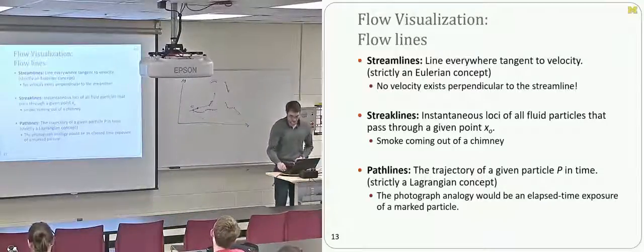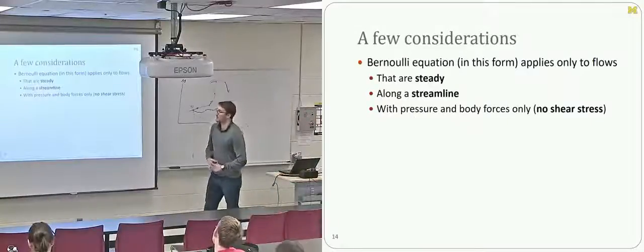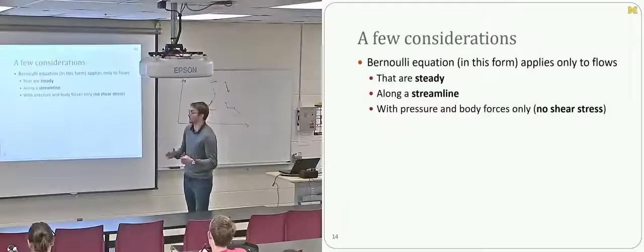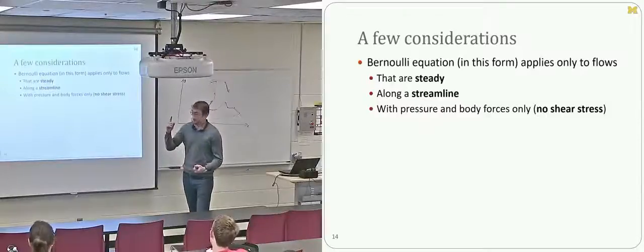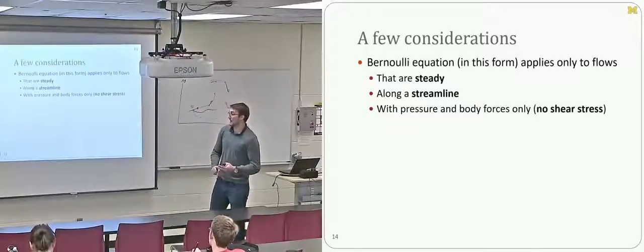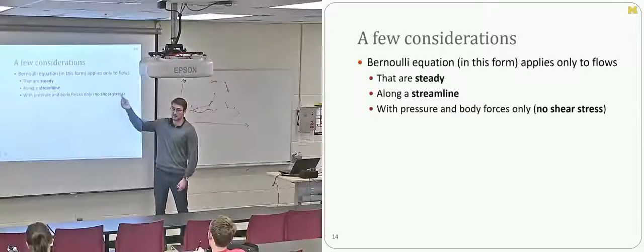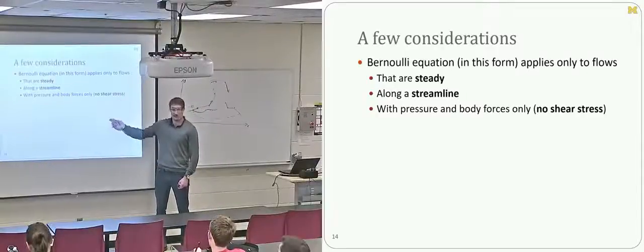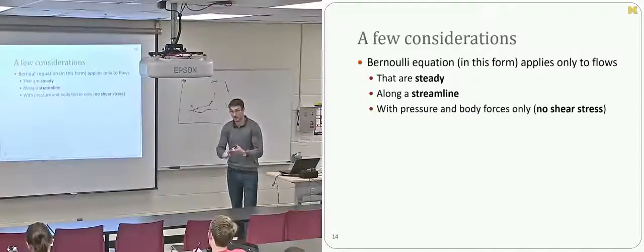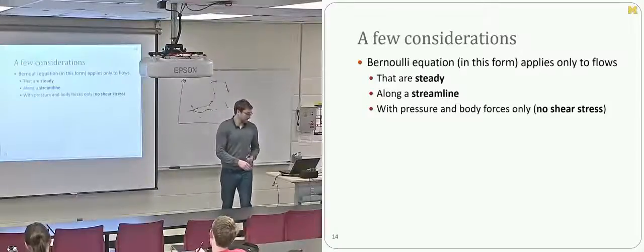It's certainly one we're going to use today. Before we really get into this, the Bernoulli equation in the form we're using today, there are other forms, requires flow that is steady, that occurs along a streamline, and flow that has shear stresses neglected. Again, we're assuming no viscosity, basically. That is, fluid particles are only acted on by surface forces due to pressure, and body forces due to gravity or some other conservative body force.